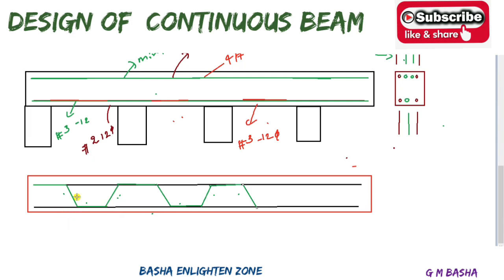If you take different textbooks, they provide the beams in different ways, but the best option is what I am telling. If 4 bars are required, you can provide complete 4 bars on the top side, and if 3 bars, complete 3 bars on the bottom side. Otherwise, you can provide minimum 2 bars completely on the top side, minimum 4 bars completely on the bottom side, and extra bars wherever required as per the direction. For example, if 3 bars are required at the supports, you provide an extra bar, and for that also there will be some calculations in the code book. The bar length will be around 0.3 L. So check the conditions once and provide accordingly.